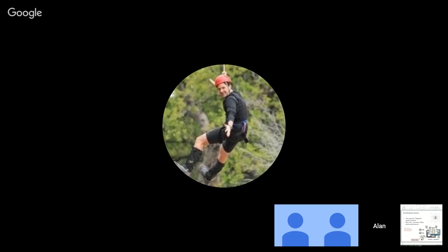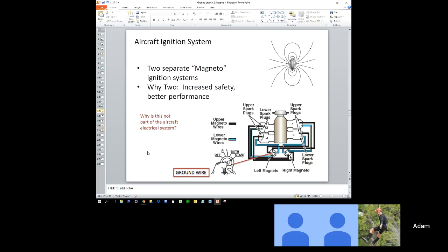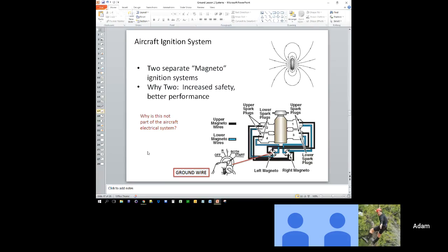So maybe not a part of this picture specifically, but on the off, right, left, both, start, what do the other things besides start and off mean? Both. Is it really like right magneto, left magneto? Why would you want to run one versus the other? Yeah, that's exactly right.